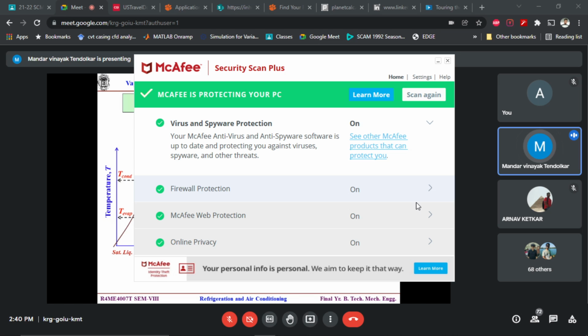So now let us try to analyze it. So I will say this extra part is the additional work required due to the superheated section. Let's say my compression starts from here. If somehow I end the compression at this point, and somehow I keep a restriction as this to be the isothermal heat rejection, and resemble it very close to the Carnot cycle. Do you agree? Yes. Correct. So that is not our case. So this A1 is that additional work required. Now who will do that work? Compressor only.